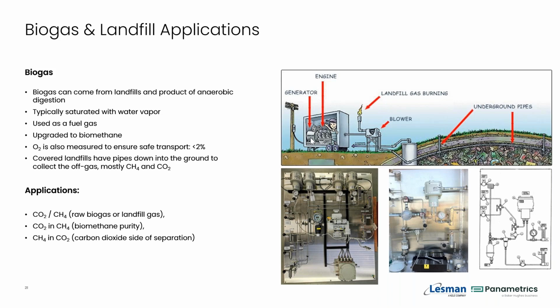The other measurement that's typically made in this case is oxygen. Oxygen measurements are used to make sure that as you're pulling gas out of these landfills, you're not sucking air into the landfill. Because if you get air into the landfill, you'll end up with an explosive mixture of oxygen and methane, and something like a spark or a lightning bolt would actually blow up your landfill. And that makes a big mess. People want to avoid that at all cost.